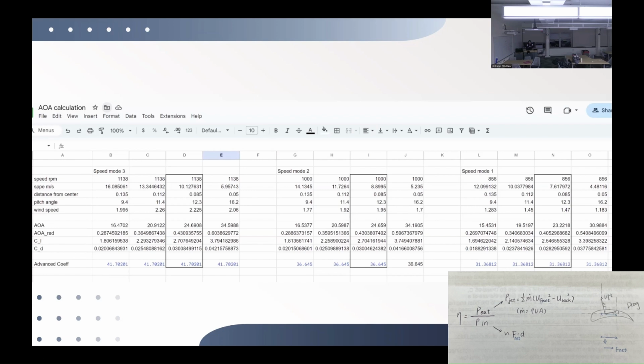And the power output is calculated by the measurement of the back and front velocity. We can tell how much energy the fan contributes to the airflow in this way, specifically in kinetic energy. Therefore, we can actually quantify which speed mode of our box fan is most optimal to work, which is the second speed mode.